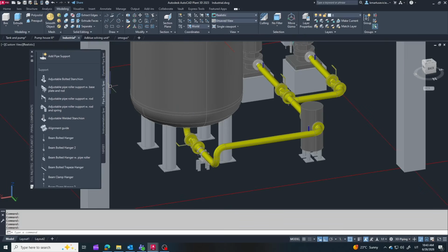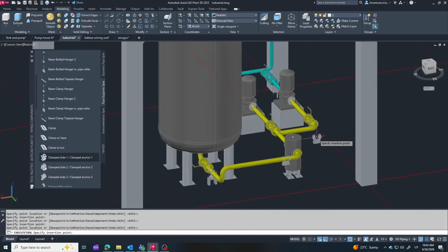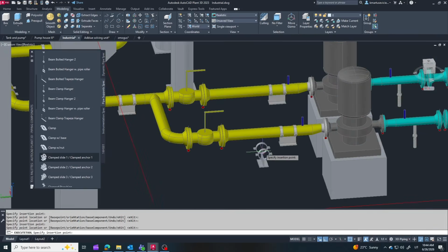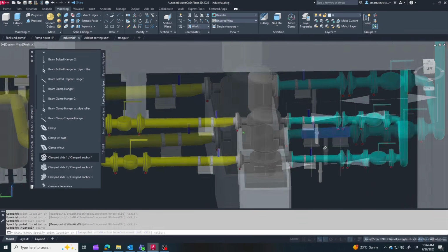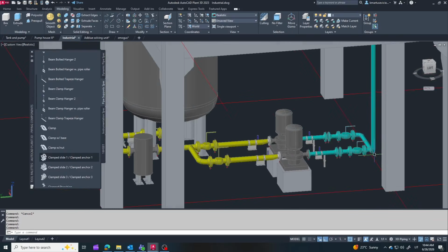Think about the structural engineer who has to attach it to the building. That's why I like routing pipes near walls, columns, or under the ceiling. It makes supporting the piping much easier and avoids long, unsupported spans. The horizontal pipe is supported for now. We'll add the steel support structure later.